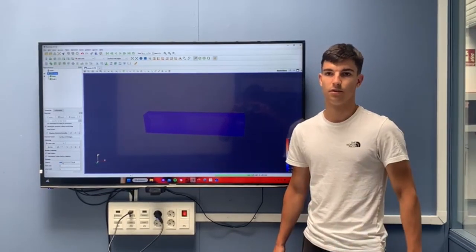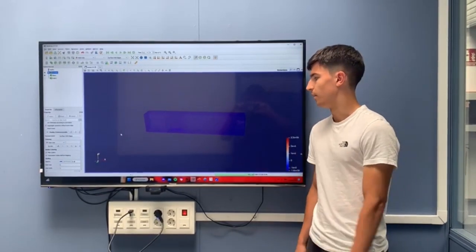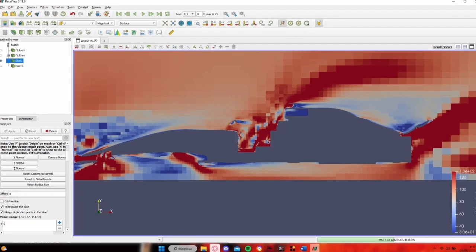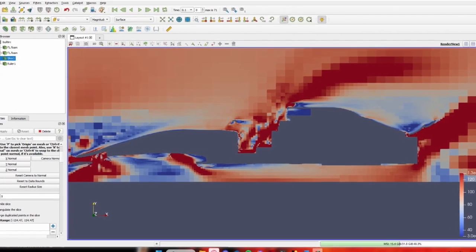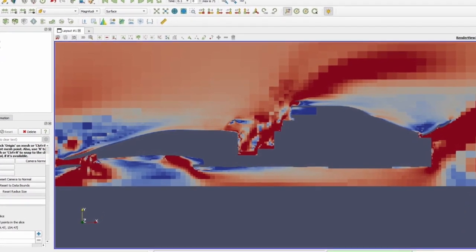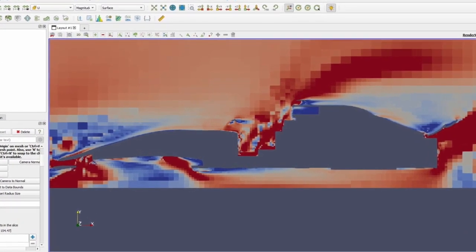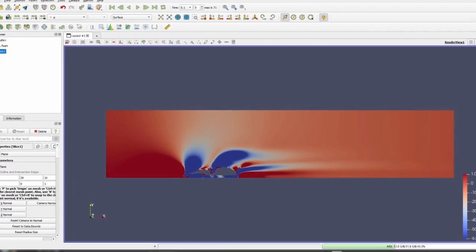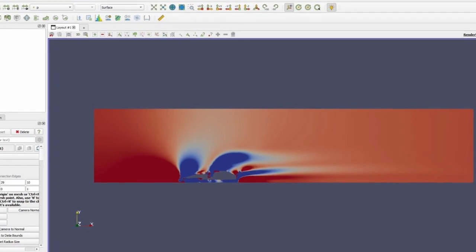The density we used is 1.225 kilograms per meter cubed, and the velocities are the following ones. Corresponding the blue color to a lower velocity, it can be seen that the expected profile was almost achieved. The velocity increases in the middle section, but due to the lack of diffuser, the velocity is still very high at the exit. Here we can see the car performed, and this is the distribution of pressures in the car.